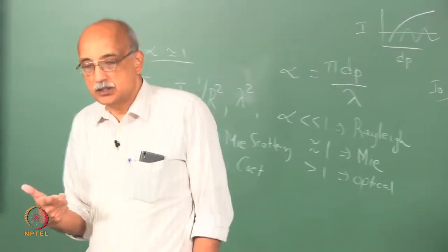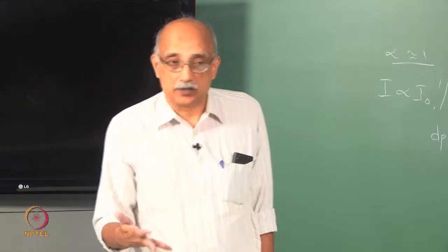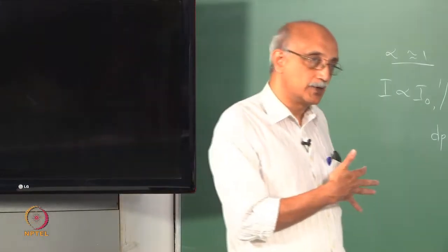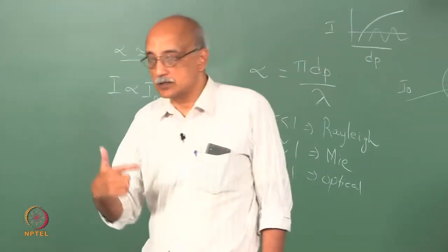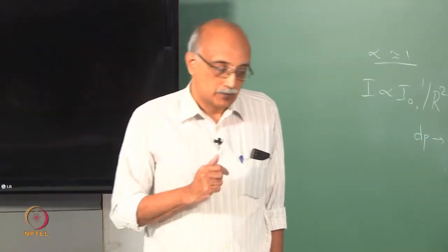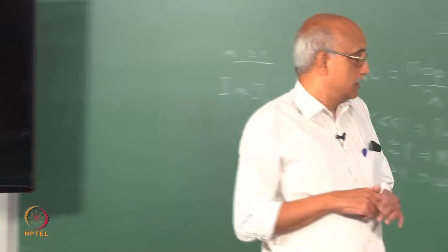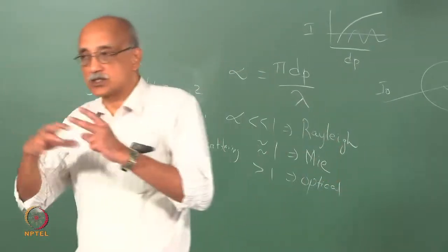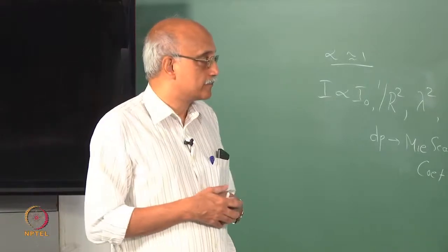Whereas repeatability is a better measure of the instrument itself, because it is the same operator. So you have kind of taken the human element out of it, and you are asking the same operator to do two measurements and report the data. So that is more a measurement of how good the equipment is, and so together they give you a very good indication of how reliable the entire process is, involving the procedure as well as the equipment.